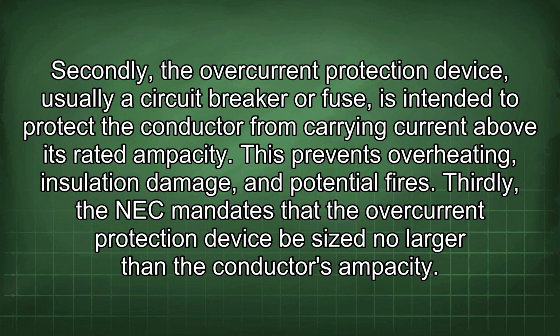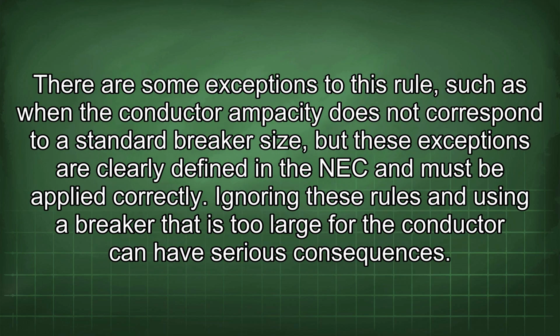Thirdly, the NEC mandates that the overcurrent protection device be sized no larger than the conductor's ampacity. There are some exceptions to this rule, such as when the conductor ampacity does not correspond to a standard breaker size, but these exceptions are clearly defined in the NEC and must be applied correctly. Ignoring these rules and using a breaker that is too large for the conductor can have serious consequences.